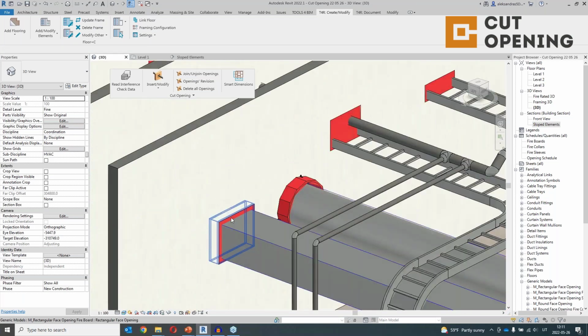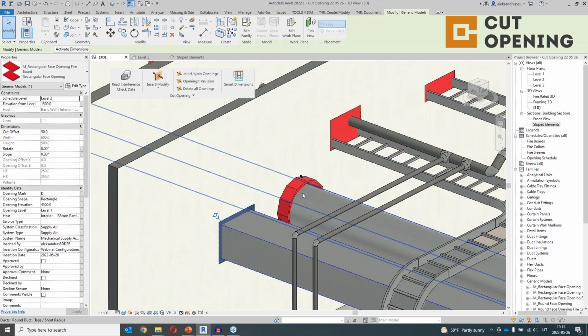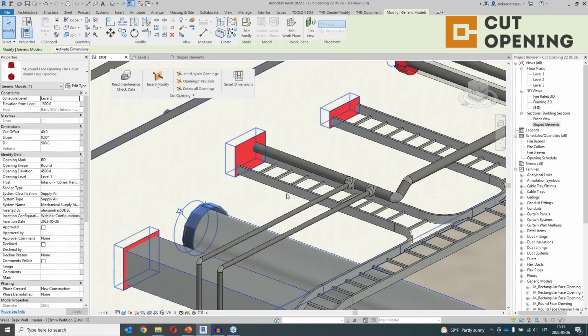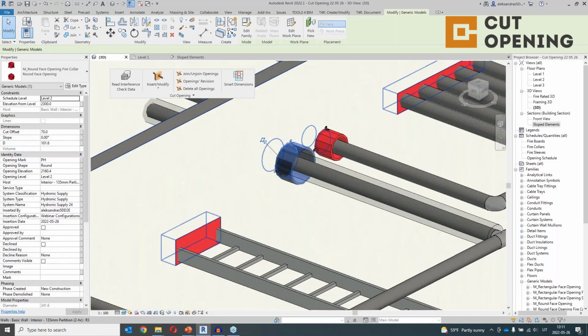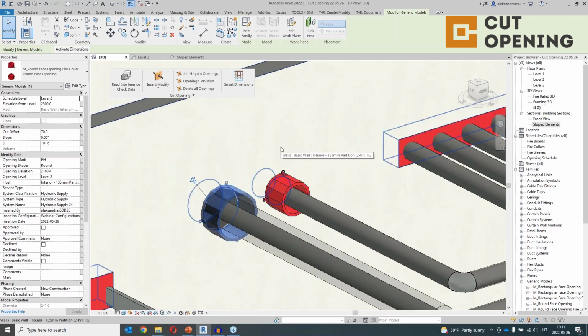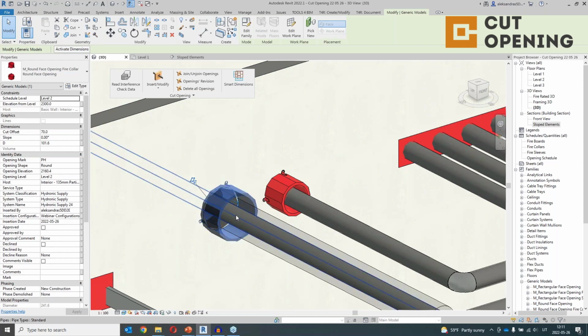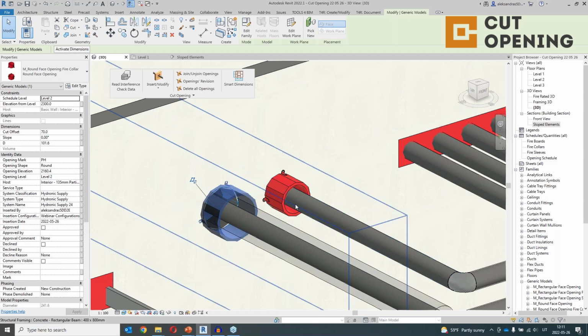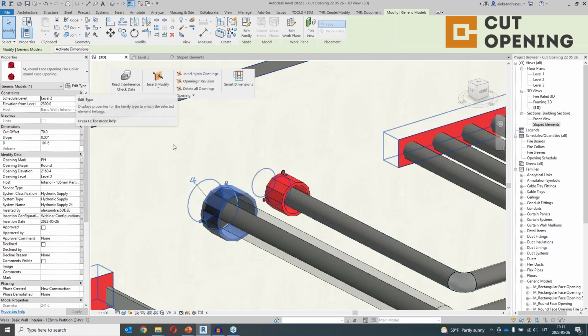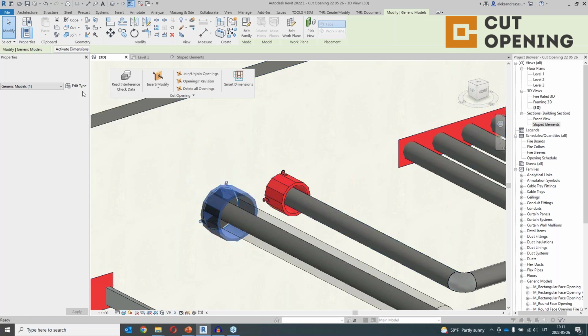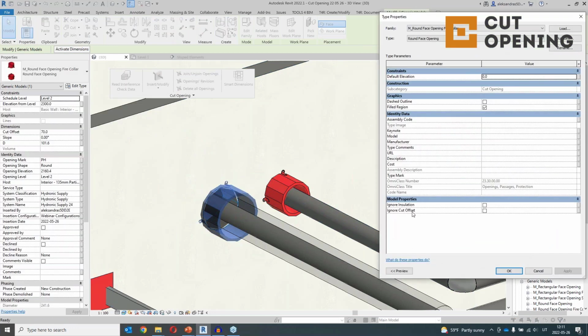So here, we see those openings. So this is the fireboards, and this is the fire collar. And here, I just wanted to mention some configurations that are available for fire collars. By default, they will be created with the same cut offset from the pipe as the opening, but you can either remove cut offset before inserting these fire collars for specific pipes and specific intersections, or you can modify fire collars themselves. I have created two additional settings.